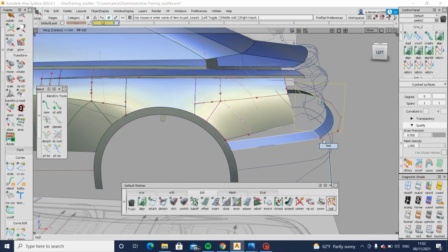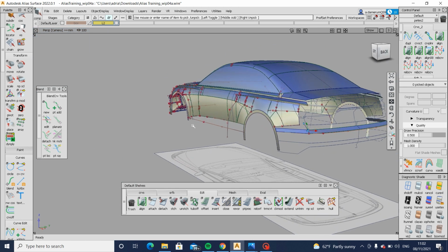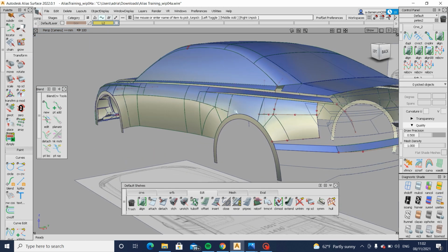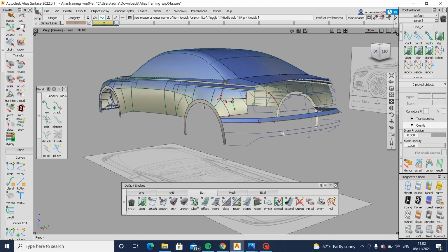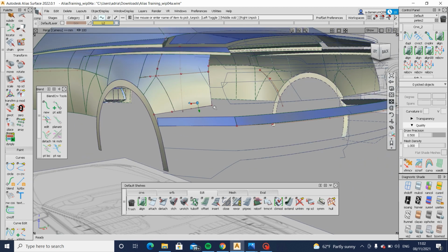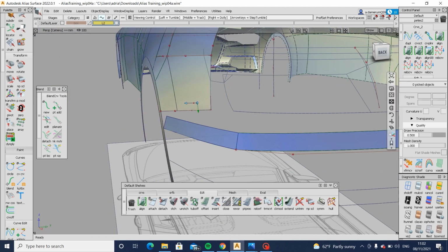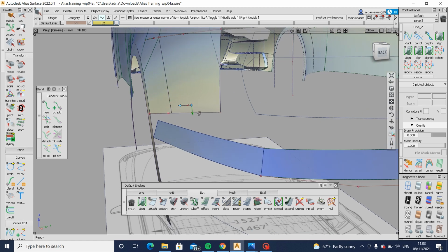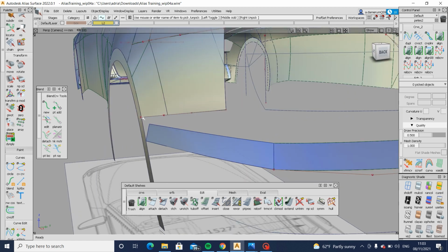Anyway, that's in. So at least we've got a guide to work to now. Let's get rid of some of these curves, they're annoying. Okay, that's better. And then we'll build this surface in here, and it's positional, and the core comes to there. So let's build down. We can do a draft again, but it does come to a point there, so let's just build a square in and work from there.